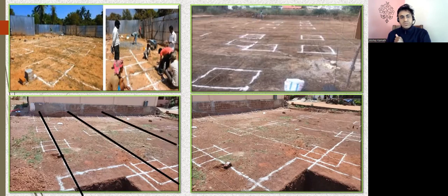These are your, let us say, vertical grid lines. And for the horizontal, let us consider this as my horizontal grid lines, the one which has gone in this way. You can see this grid. They are not drawn completely, but it's okay, right? So these are your vertical grid lines. Same thing you can see here, no? These are your grid lines in this direction, and these are your grid lines in this direction. Got it? So this is how you have to understand the structural drawings, and this is how practically things are done on the site.